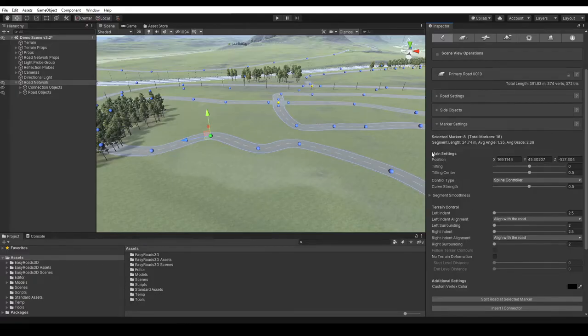As we already saw, when we want less detail in a section, we can remove the selected markers using Shift-R. To add more detail to a road section, markers can be inserted with the I key. The new marker will be inserted at the mouse position. The hotkey section in the manual is a useful resource for this type of options. The rightmost Info tab in the inspector toolbar includes a direct link to this page on our website.